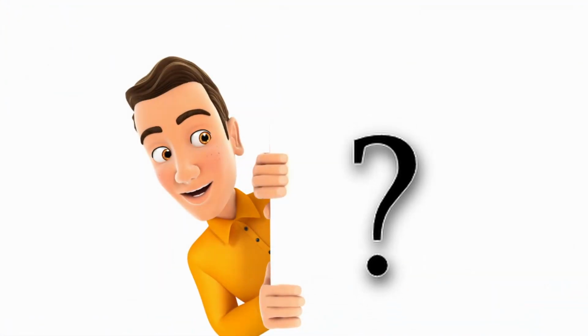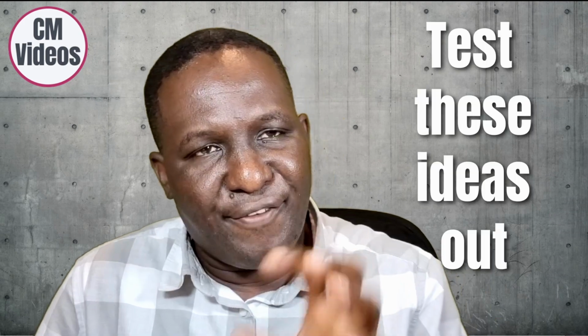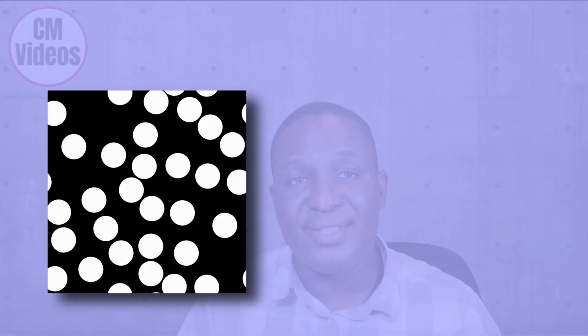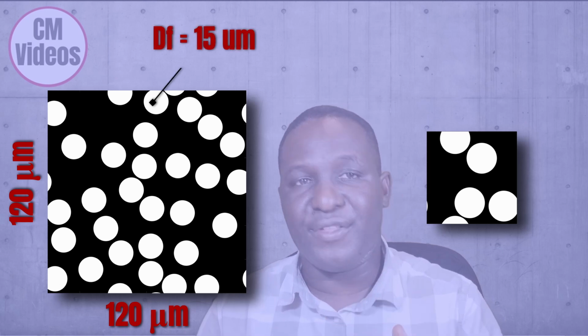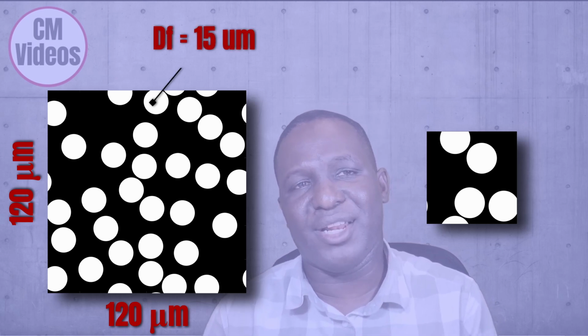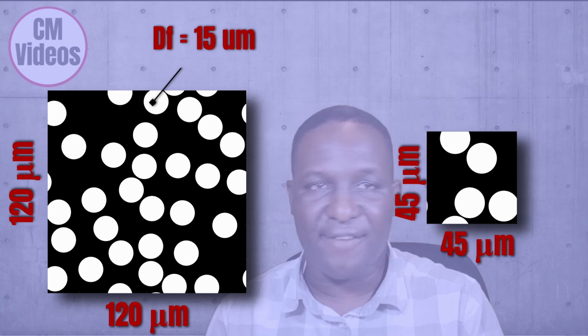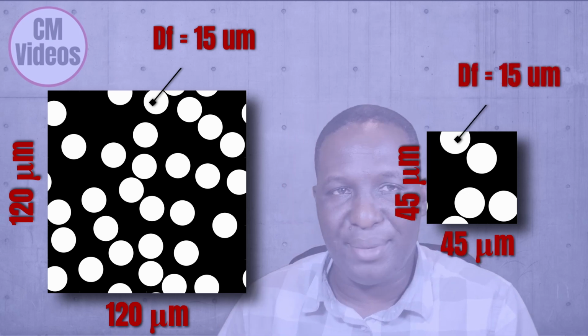And so Stephen is a bit unsure as to what to do, and so he decided, okay, I'm going to test these ideas out. The first thing he wants to do is to create two representative volume elements according to each of these guys that have advised him on what to do. So we have a large representative volume element and a small representative volume element. The large representative volume element will be of size 120 by 120. The fiber will have a diameter of 15 microns. The smaller representative volume element will have a dimension of 45 by 45 with exactly the same fiber diameter.